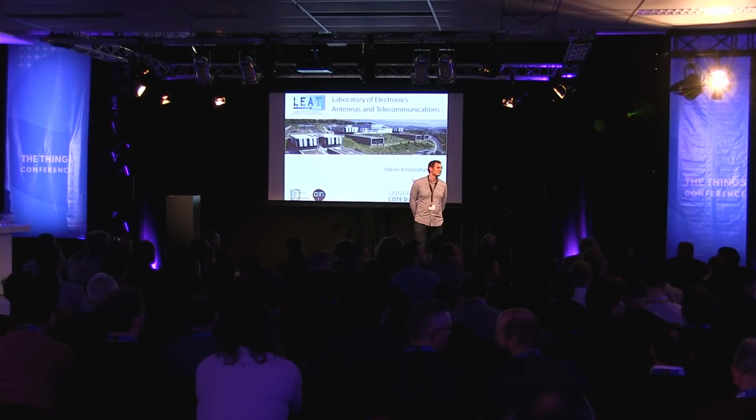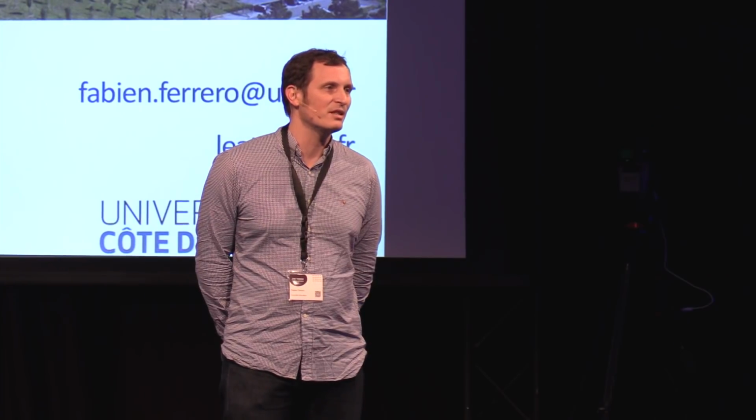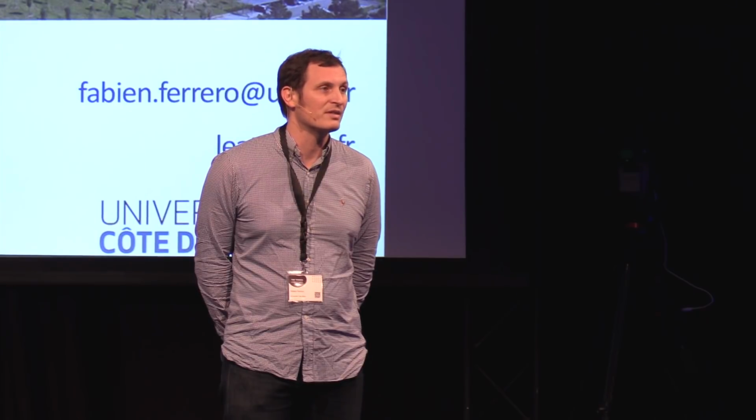I can get the data, but I stay close to it. Yeah, pay attention, because with LoRa you have such good sensitivity that when you are close to your device, it's always going to work. Then you have to look at whether it's still working when you go longer distances.